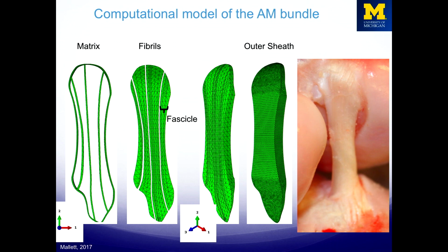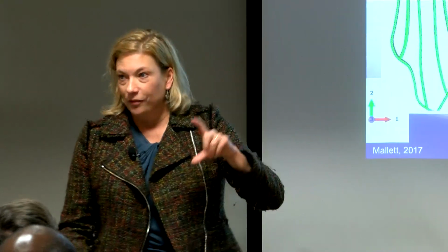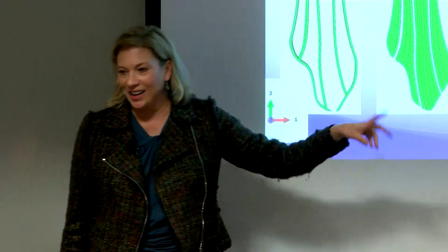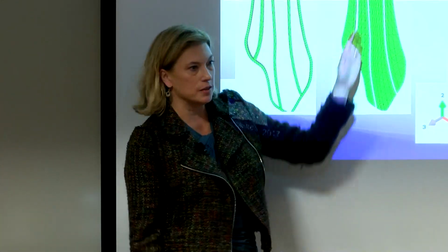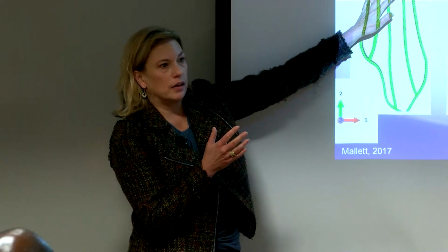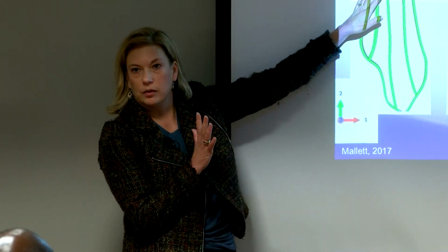Those fibrils are combinations of fibers, and those fibers are combinations of individual collagen molecules. Well, okay, in finite elements we can't get 4 orders of magnitude of hierarchy in our model, but we can get 2. So we could model the collagen fascicles and fibrils as anisotropic nonlinear materials, and model the matrix as sort of an isotropic material.